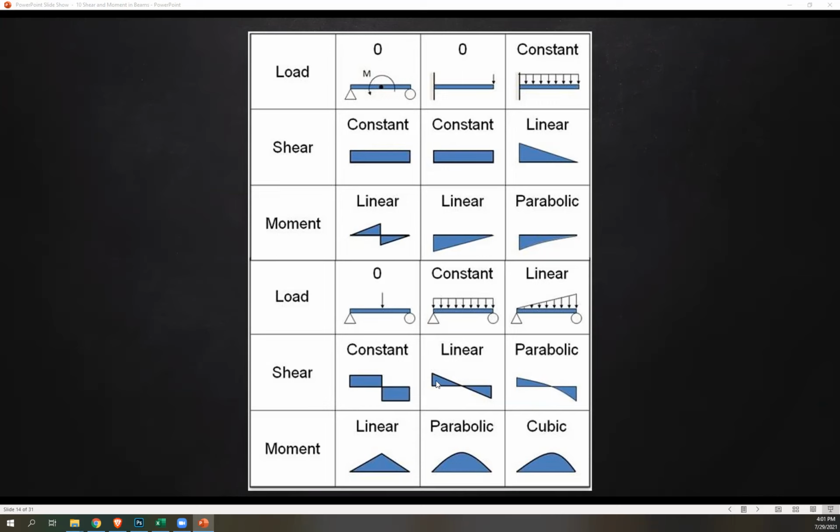Okay, same thing here, you're going to go upward, and then this is a straight line. You're going to go slanted downward, and then up again. Okay, and then this is almost the same here, but instead of a straight line or slanted line, you have a parabolic line. Then moment of this, so this is positive, so your slope will be upward. And then it turns into a negative area, so slope is downward. And so on and so forth.